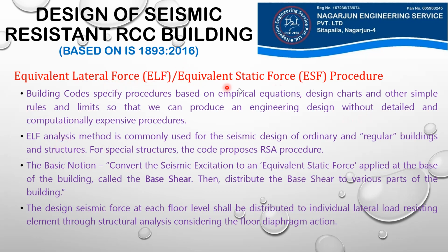So equivalent lateral force or equivalent static force is based upon the design principles of a building code. It is a building code specified design procedure. The ELF analysis method is commonly used for the seismic analysis and design of ordinary and irregular buildings and structures. What are the limitations of this method? We will be seeing this when we look at the code. The code prescribes the situations in which we can use this analysis technique. For special structures, the code proposes the response spectrum analysis procedure. We will also be looking at this design process in this course.